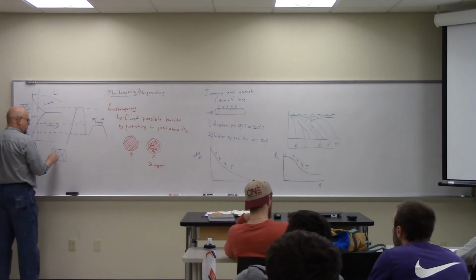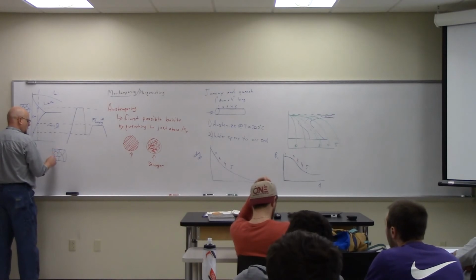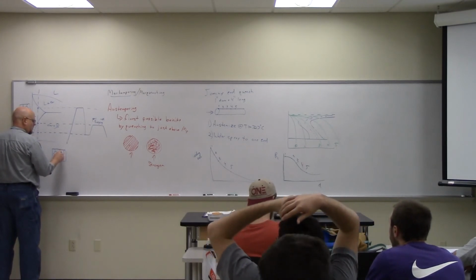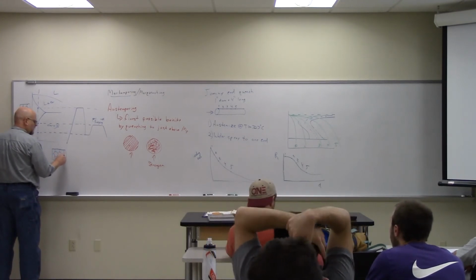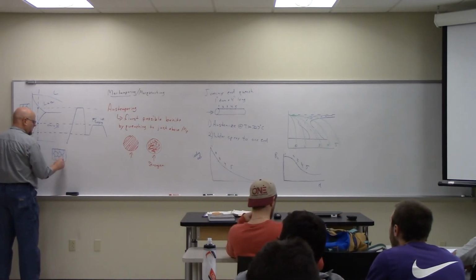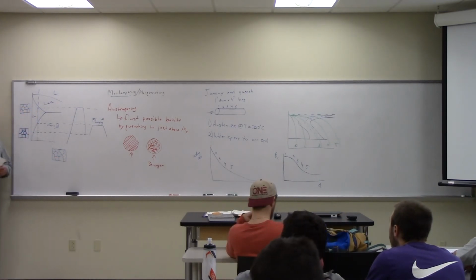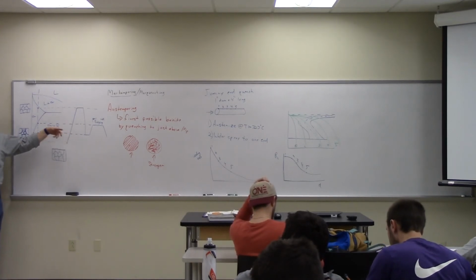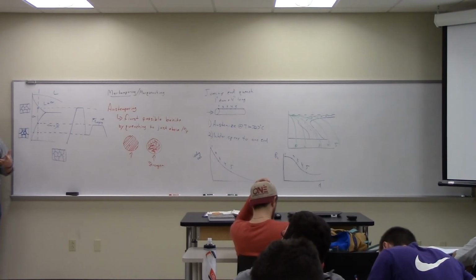I start to get beta forming out in the middle of the alpha grains because I just get tiny little bits forming. And so I don't have to worry so much about diffusion driving the process, because there's so little of the bits that are forming beta that I don't have to diffuse large amounts of B material, whatever the B material is, someplace to get the beta to form.